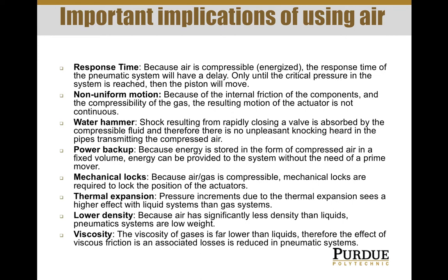Pneumatic systems, compressed air systems, can be used as power backup because you can store that energy in a vessel, in a reservoir. Say you lose gas power or electric power, and you have some energy stored in the form of pressure in a vessel, then you can use that energy to unlock a system. And so as a backup, it can be used.